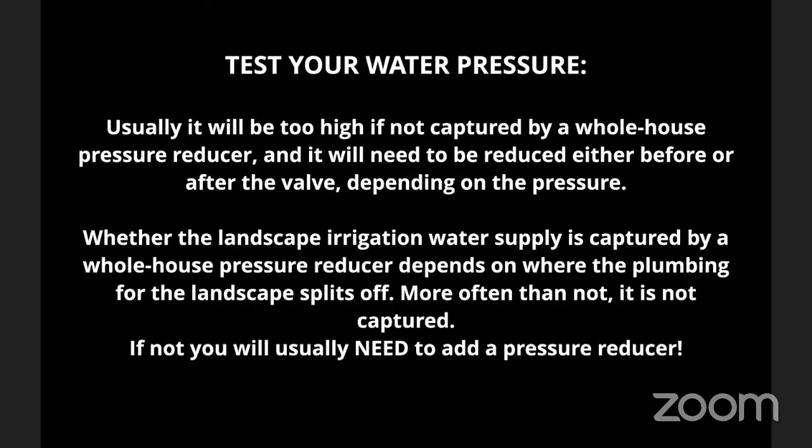However, it is best, so kind of presenting best practices, to test your water pressure with a pressure gauge that you can get at the irrigation supply store.